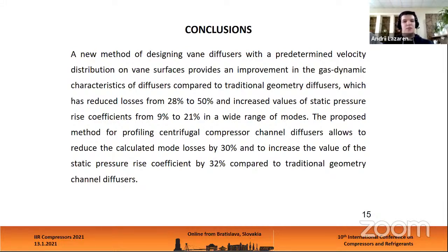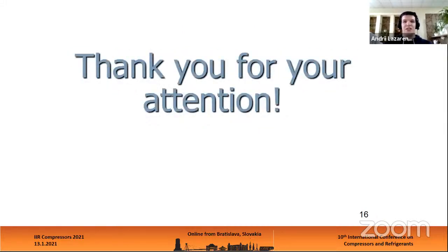The proposed method for profiling centrifugal compressors channel diffusers allows to reduce the calculated mode losses by 30% and to increase the value of the static pressure rise coefficient by 32% compared to traditional geometry channel diffusers. Thank you for your attention.